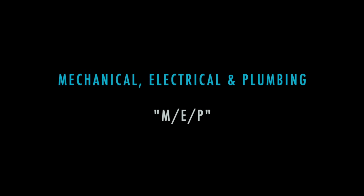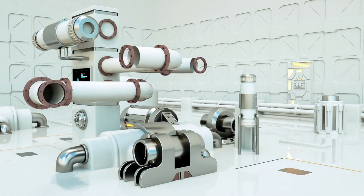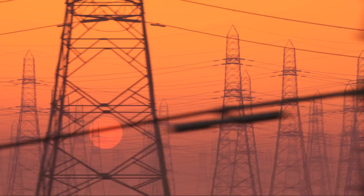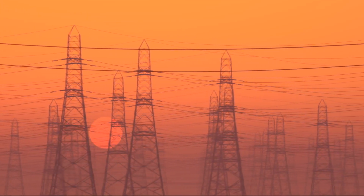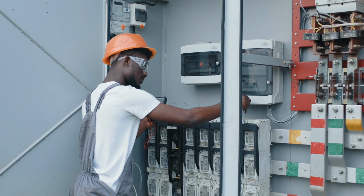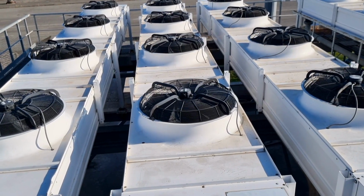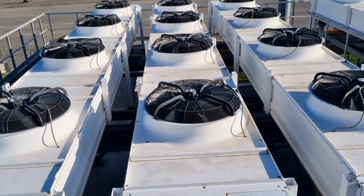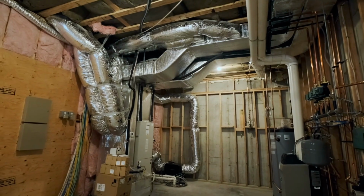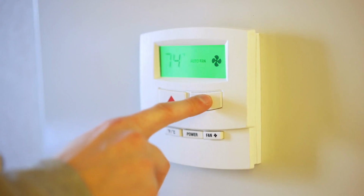The next category we're going to discuss is actually three separate trades, although they all often fall under the umbrella of MEP, which is to say, mechanical, electrical, and plumbing drawings. Electrical drawings will depict things such as transformers, electrical panels, wiring, fixtures, outlets, and anything else related to power. This can include power required to run machines and other units that fall under the mechanical and plumbing categories as well. Mechanical drawings will depict things such as ventilation, heating, air conditioning, fans, and other ancillary items, not the least of which are thermostats and other controls required to run this equipment.